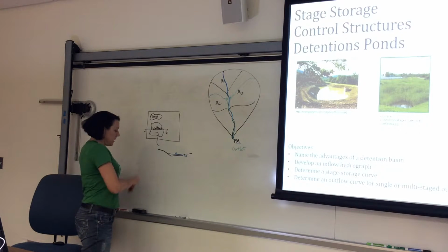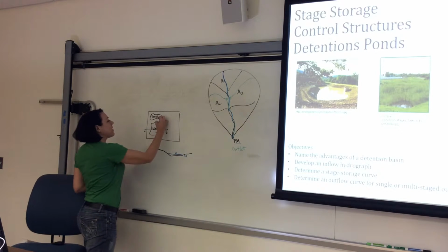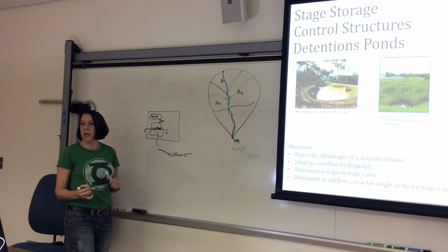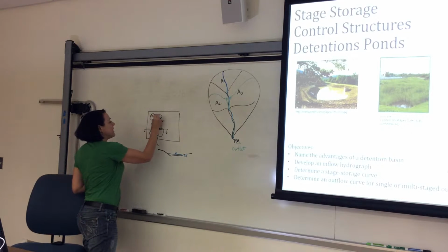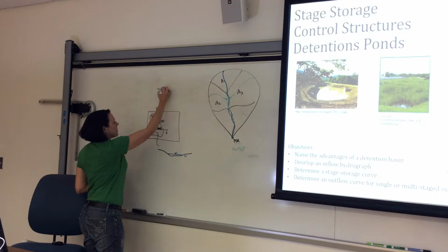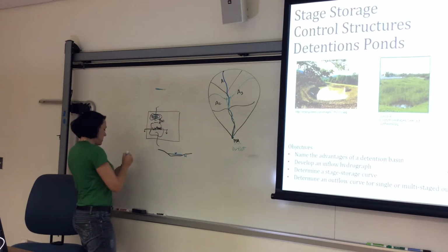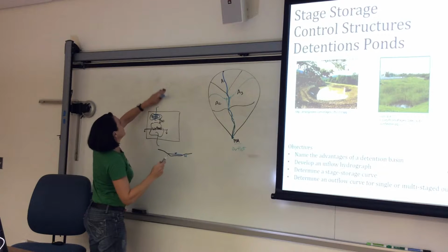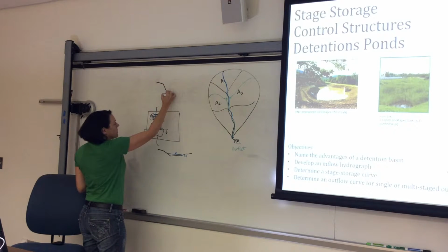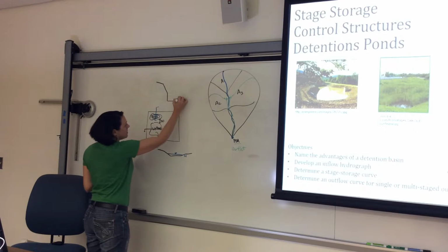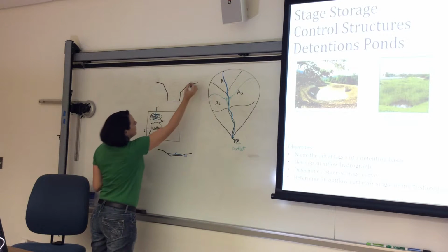Now, we'll say that there is maybe 50 feet between the wetland and the pond. If I did a cross-section of the pond, top of bank, 4-to-1 slopes, 2-to-1 slopes, okay?